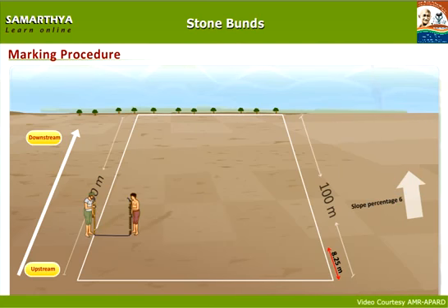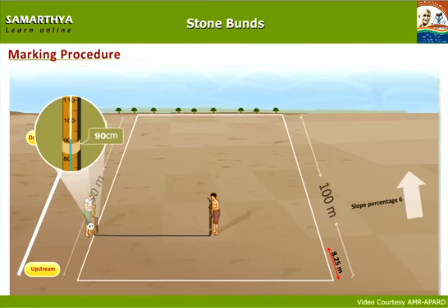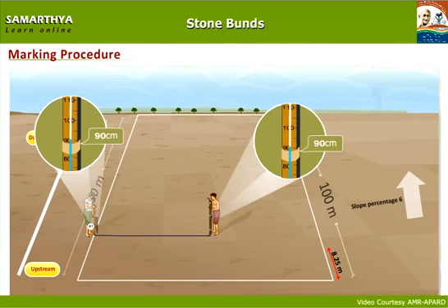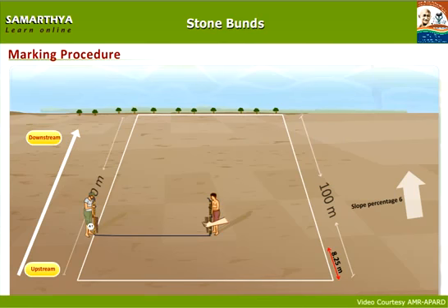Place one side of the hydromarker at one side of the field and mark it as A1. Starting from one side of the farm, place the hydromarker and stretch it to the second end. Adjust the second end of the marker until the water level is equal. Place a stick and mark it as A2.